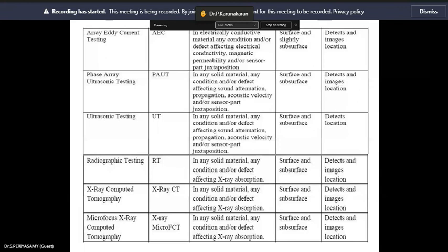If you are building in the vertical direction, it will go down. It is not wetted with the other particles or the other layer. It will go on. In such cases, you can get an end effect. Using radiometric analysis, you can find the end effect, the undulation, then the coarse finish, etc. Then with the thermal images, you can go for a full temperature analysis, on what happened, the melt pool, what is happening.